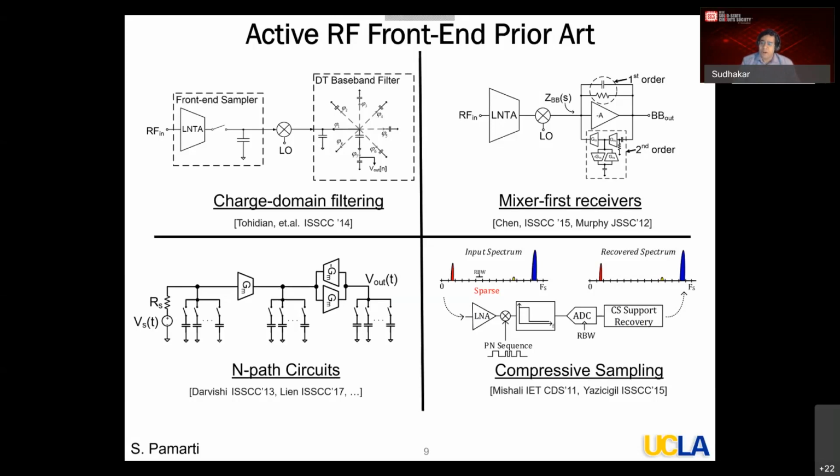The out-of-band filtering is somewhat limited, although there are new interesting approaches on that. Professor Bram Nauta's group and Klumperink's group in Europe have done some really interesting work where they have demonstrated outstanding linearities, on the order of 45 dBm IIP3, if I remember correctly. So there's a lot of interesting work going on in this area.